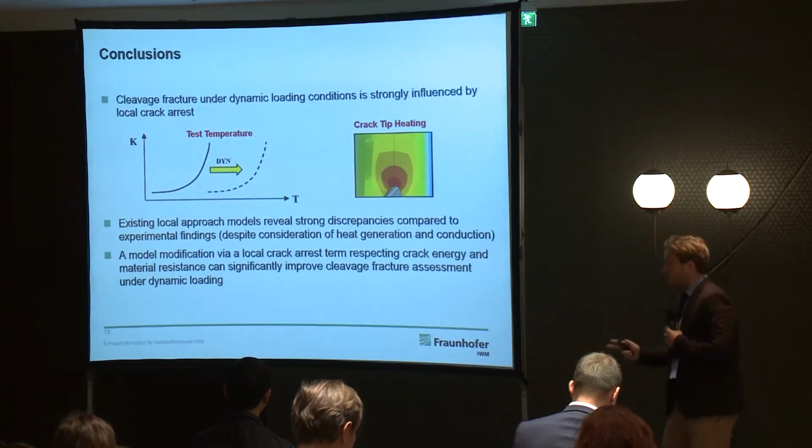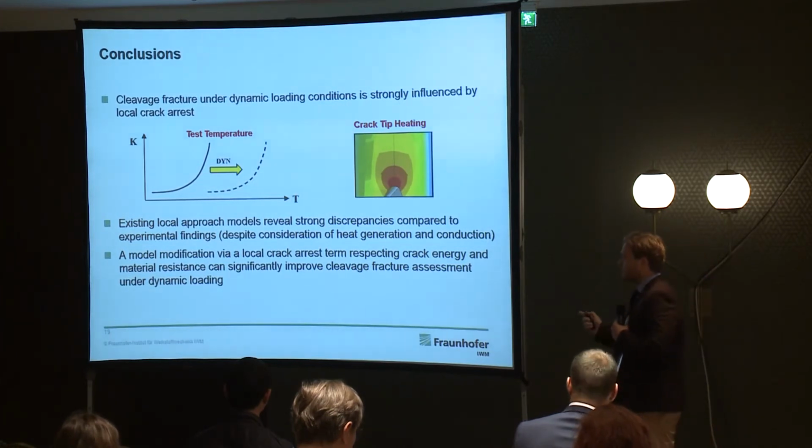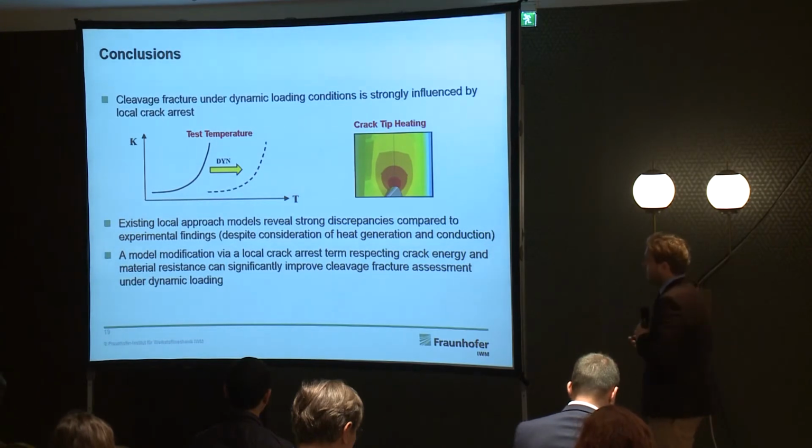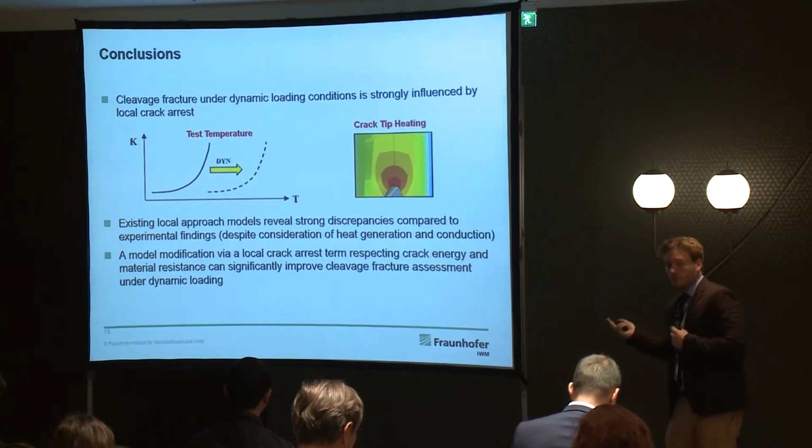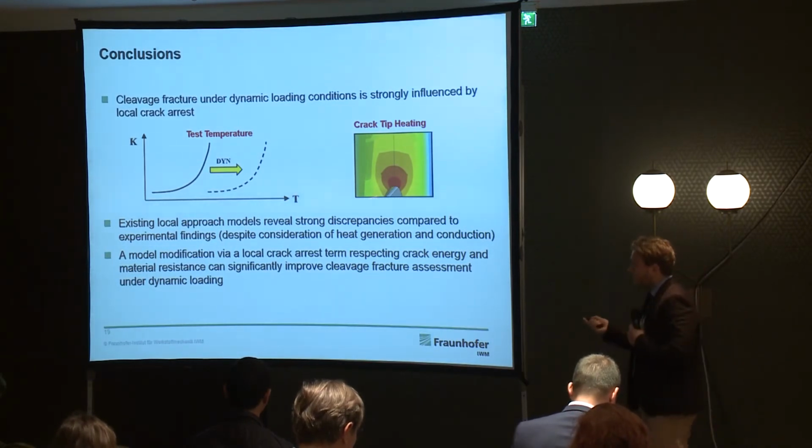Okay, so last slide, conclusions. The things that I want you guys to take with you is, for one, cleavage fracture under dynamic loading conditions is strongly influenced by local crack arrest. The question is now, why is it not influenced under quasi-static conditions? Well, there's two reasons. Both are linked to temperature.